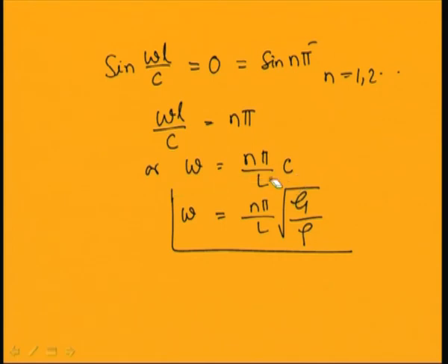So, in this case you can observe that the nth frequency is n times the fundamental frequency of the system. So, in case of torsional vibration of this fixed rod, the nth vibration will be n times the first mode vibration. So, the corresponding mode shapes you can write: phi n of x is equal to b n sin(omega x by c).